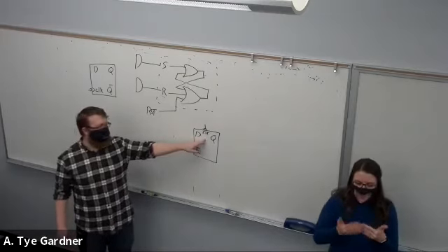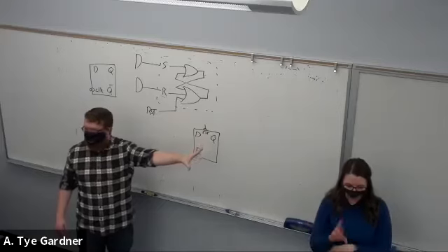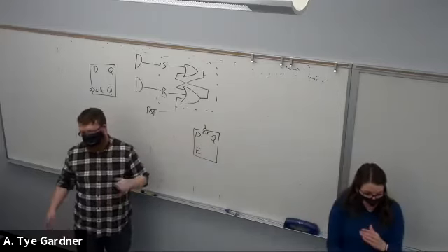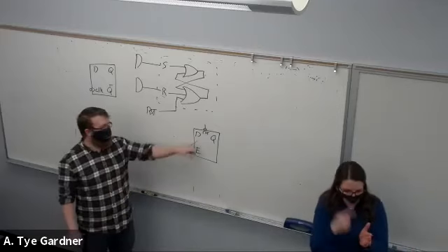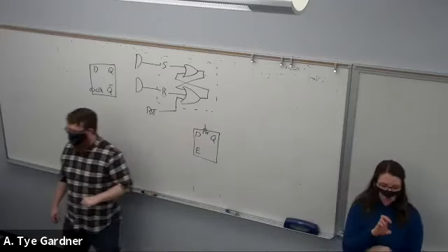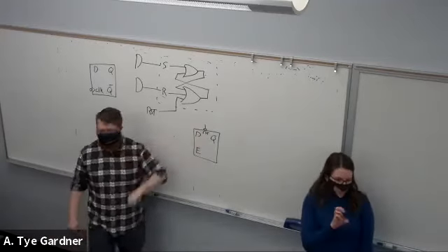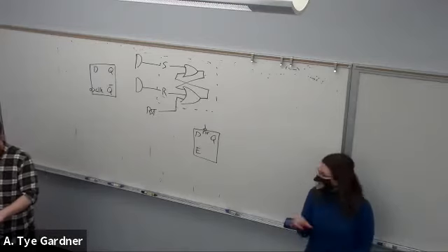It also means that you can have downstream error detection if you lose power, because they just go to a reset state, which is beneficial. So you'll see these active low resets most of the time. If you didn't want an active low in the drawing, you just erase the inversion bubble and ta-da, you've communicated the same idea.